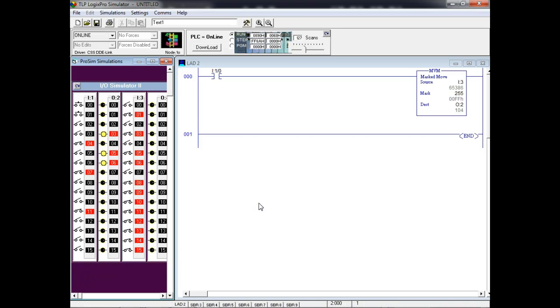So are you okay with a move with mask? Yes, no? The only thing different between an actual move and a move with mask is the move with mask actually does an AND mask too. You can't do an OR mask here. We use ORs to make sure certain bits in our answers are set, right? We use an AND to make sure certain bits in our answer are always cleared. Move with mask is always just an AND mask.